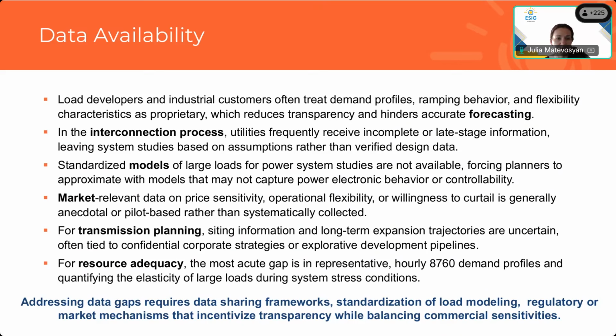There are no standardized models for large loads. This is still an active area of research and development, but what's happening now is that system planners are using models approximating the behavior of these power electronic loads. And again, that can be either overly conservative or may have potential reliability risks. Market-relevant data on price sensitivity, operational flexibility, or willingness to curtail is generally not available and is not systematically collected. So this is something that's really needed.